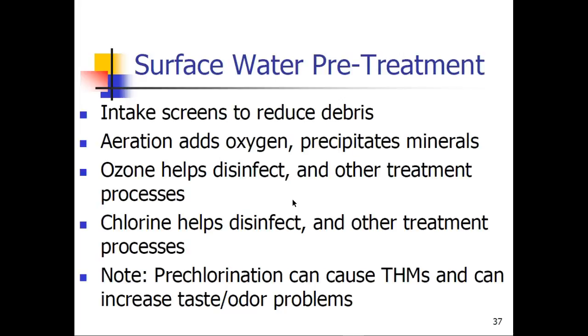Aeration adds oxygen and precipitates minerals. Ozone helps disinfect and other treatment processes. Ozone is something that you can use for taste and odor, but you can also use for disinfection. Now, the thing with ozone is it does not last. There is no residual. It is an instantaneous kill, and after that, the water can become contaminated again.